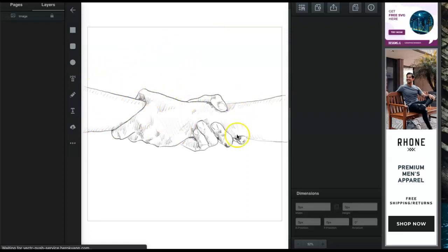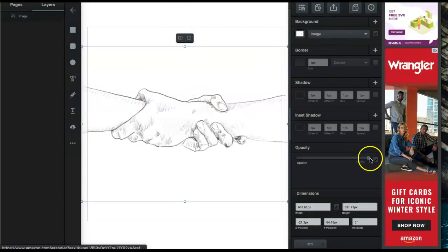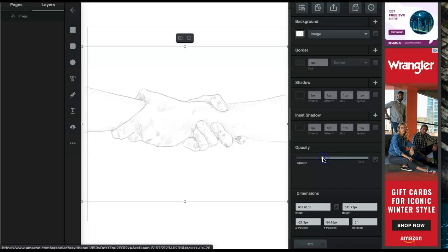and moved it. Another thing that you could do, with it unlocked, is select it and bring the opacity down a little bit. So if I drop the opacity just to fade it a little bit, if I'm using a black line, now it'll show up better. So again, I use the opacity to lower the clarity of that image, so it makes it easier to trace. And I'll click the lock again. Then I'm going to choose the pen tool.